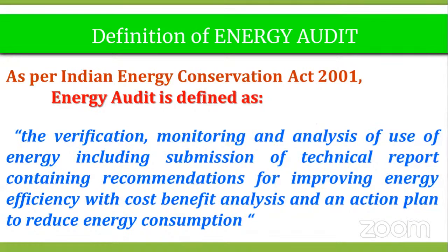So that means verification. The data needs to be verified. Where it is working, what power it is utilizing, how many hours it is running, whether it is running with frictional losses, whether many losses have accumulated, and whether the pump is an efficient one. All such things need to be verified. And it needs to be continuously monitored, not for 1 or 2 days, because due to weathering and frictional losses, there may be a lot of deterioration to the actual equipment. So we need to monitor it regularly.